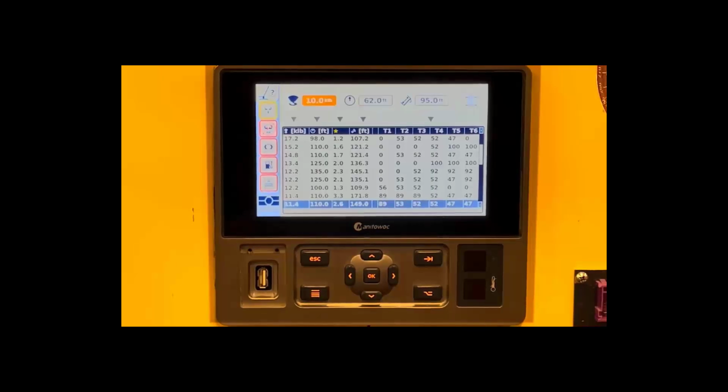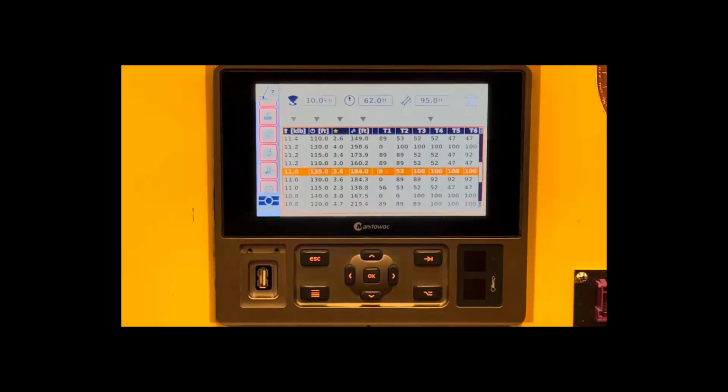So down below, we have all the different boom configuration scenarios to select from. We highlight this area and select it with the jog dial. Now we can scroll up and down to see all the different configurations. We scroll to the top. We see the top row is showing us the first selection we have is 25,000 pounds capacity, 90-foot radius.